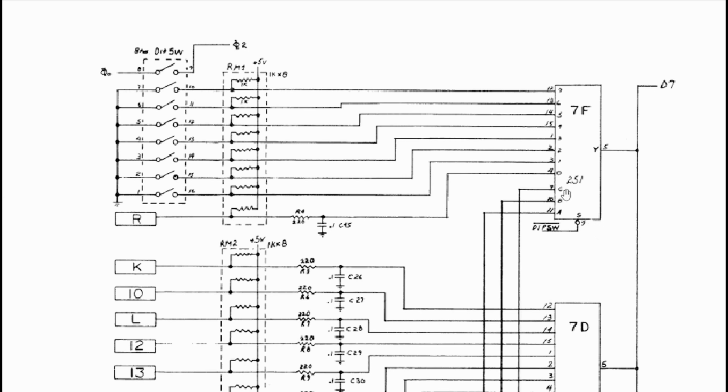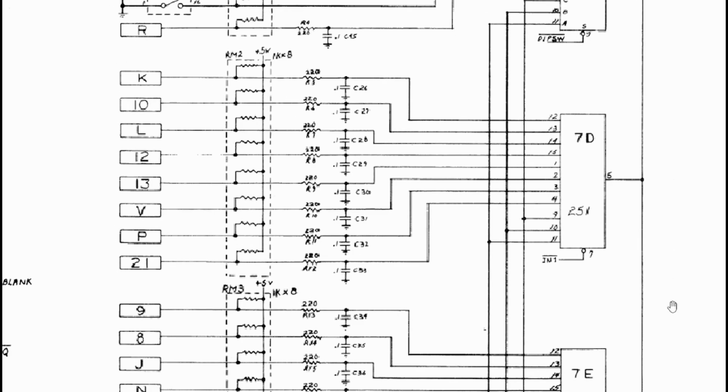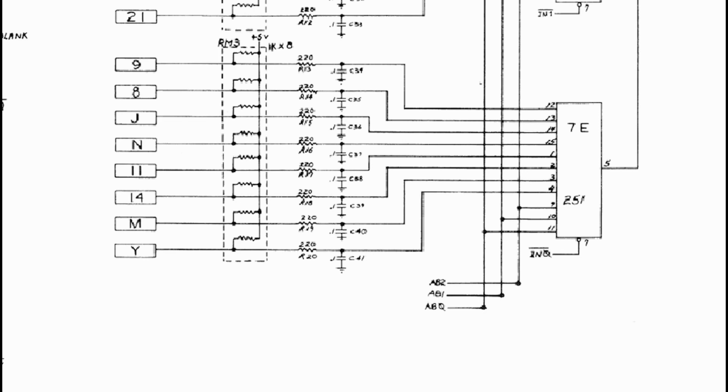We have 3 inputs ABC, which allow the correct control to be addressed, and then each dip switch is connected to an input pin 0 to 7. Depending on the selection address, the output Y is carried through from the relevant input. This is then connected to the D7 pin that goes into the CPU, which is the highest data pin. The functionality is the same for all 3 groups of input pins.